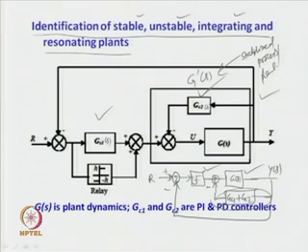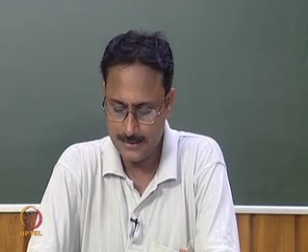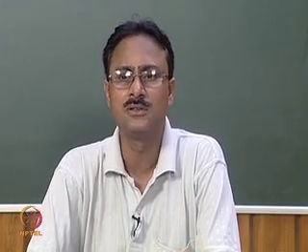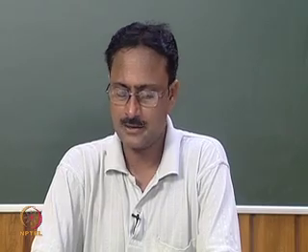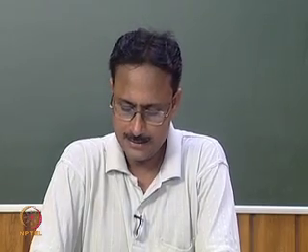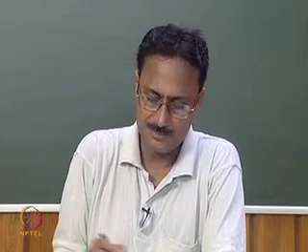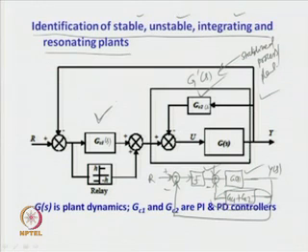So, from here we can make out that in spite of the presence of static load disturbance or external disturbances, the relay will successfully be able to generate limit cycle output, and from there using the measurements we can tune the parameters of both the controllers GC1(s) and GC2(s). So, this is what we get from this new identification and control scheme.